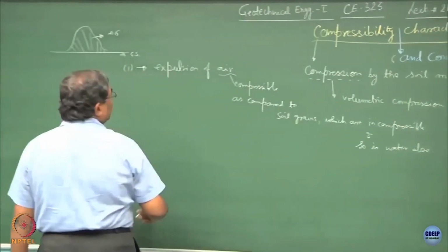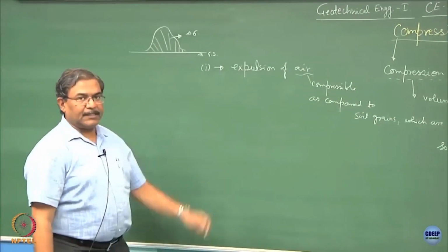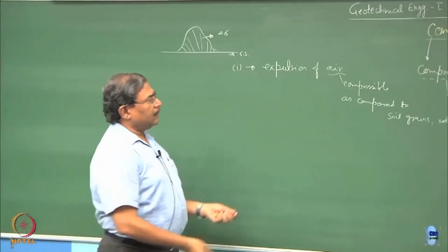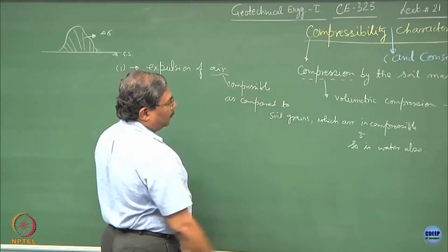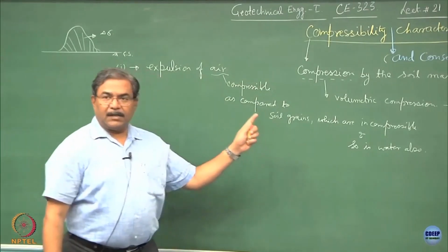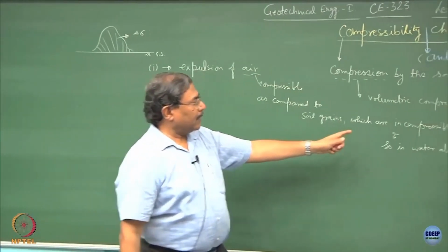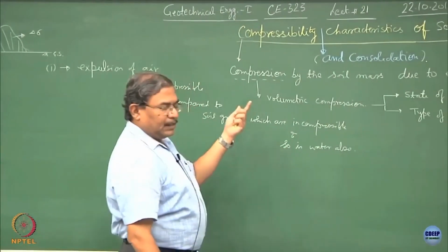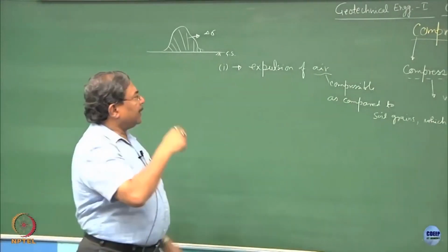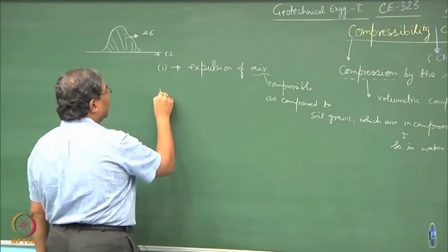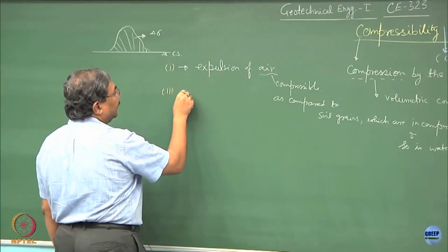If I am dealing with the dry soil and if I load the dry soil system, the chances are that the air, being compressible, will go out, but the soil grains, which are incompressible, are not going to be deformed. Alright. However, when I change the scenario, I will be talking about the third case directly,